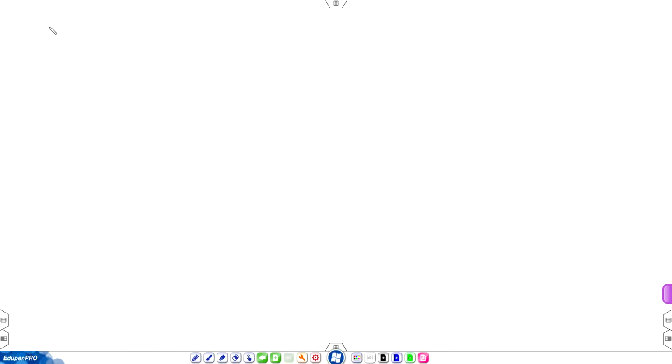So, completing these calculations, pi 1 will be L over d, pi 2 is equal to epsilon over d, pi 3 will be mu over rho u d. Now, you recall from your Moody's chart that rho u d over mu, what is it? Reynolds number. Do not say Renault, it is Reynolds. The name is so important for us, we have to pronounce it properly. Reynolds number.